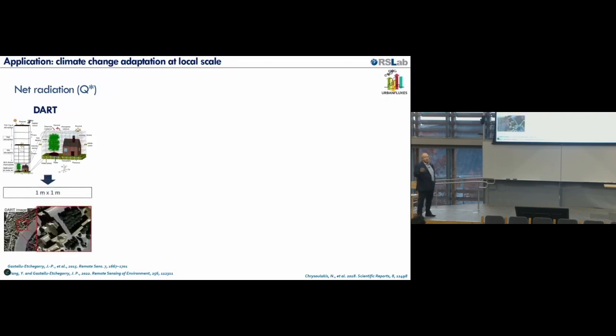And we can model the albedo at 1 by 1 meter. So the albedo is the total reflectance, but we have also the angular integration. The problem is how to go from 1 by 1 meter to the neighborhood scale, let's say 10 by 10 meters. Because this is not just a linear upscale, because we have the effect of the bulk albedo and we have the multiple reflections.